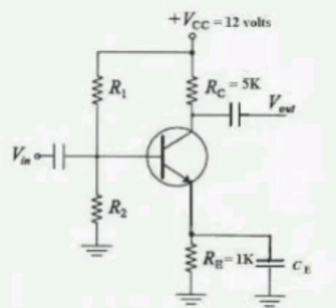Increased impact of harmonics and distortions. Low power factor systems often experience increased harmonics, especially with non-linear loads. Harmonics cause deviations from the ideal sinusoidal waveforms, making accurate measurement and analysis more challenging. Effect on power quality: harmonics can distort voltage and current waveforms, leading to errors in power calculations and reducing the accuracy of power factor correction equipment.